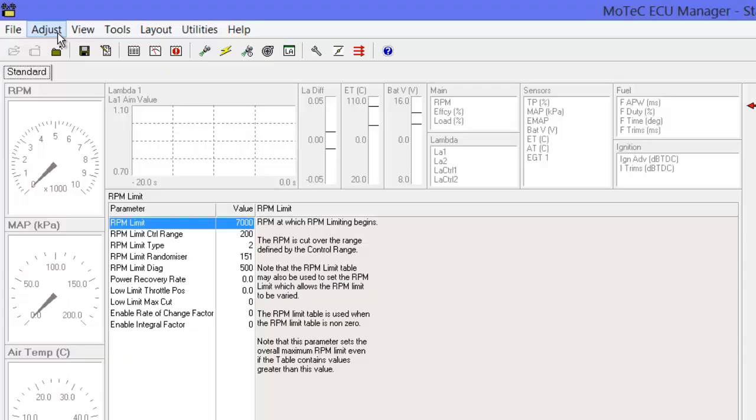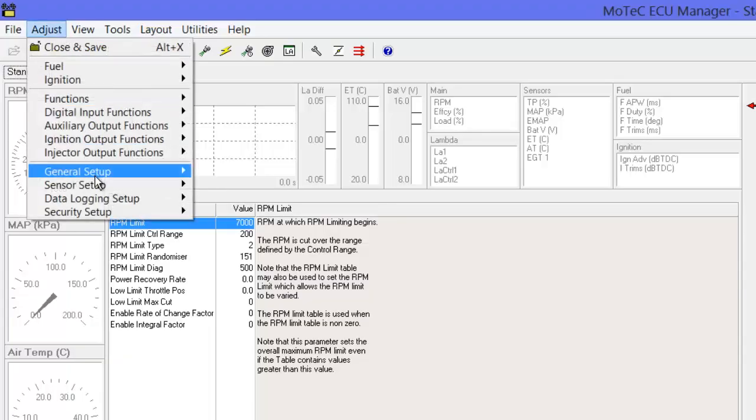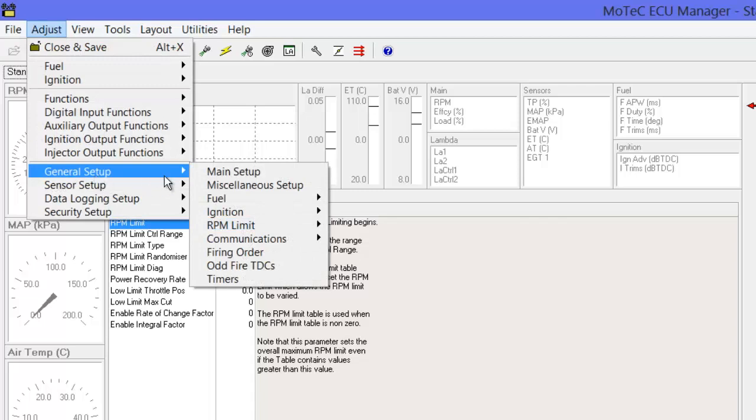The way the M150 deals with the injector setup is quite advanced and still not too common, so we're going to look at the settings in a more conventional Motec 100 series ECU too. In the 100 series, the injector operation mode is defined partially by the trigger mode the engine uses. Where possible, we want to use sequential injection, where each injector is operated separately, and this requires that the ECU has a sync input to tell it where in the engine cycle it is.